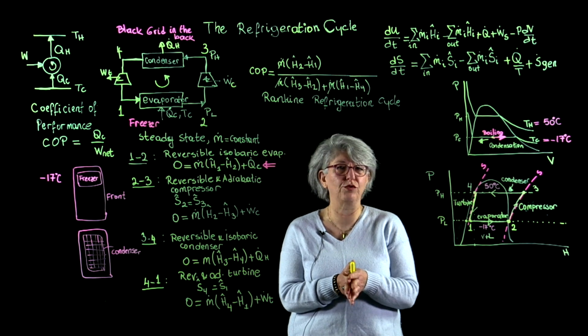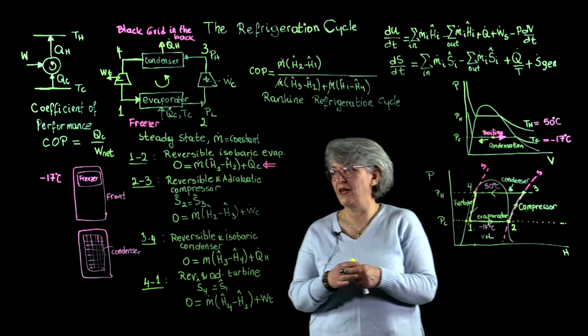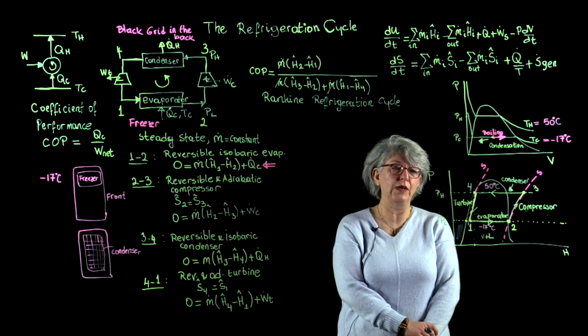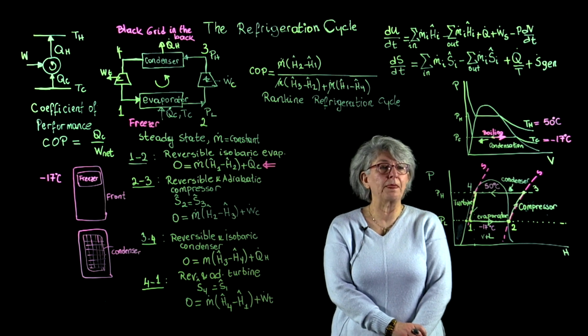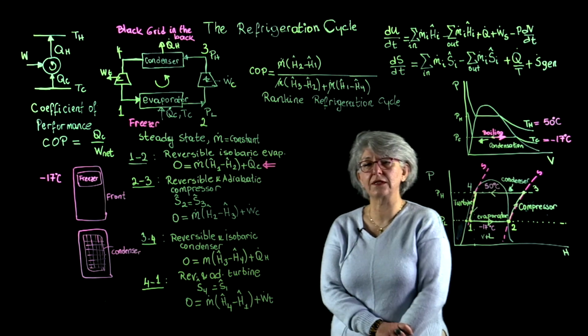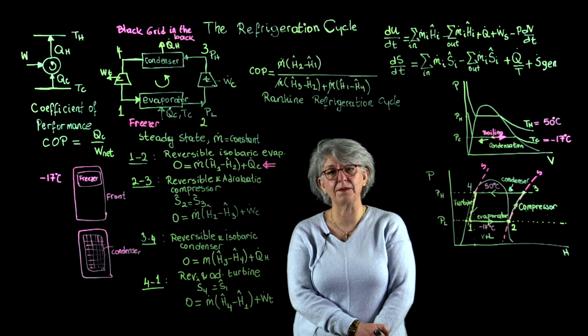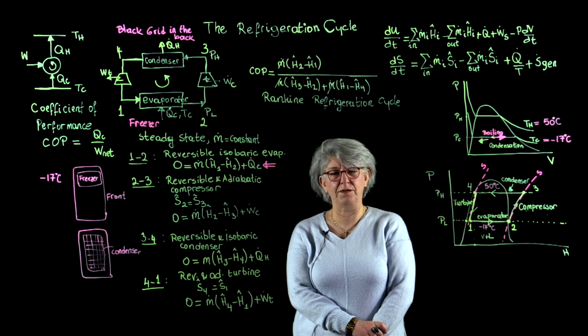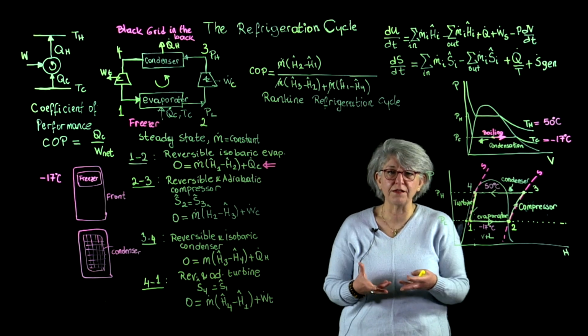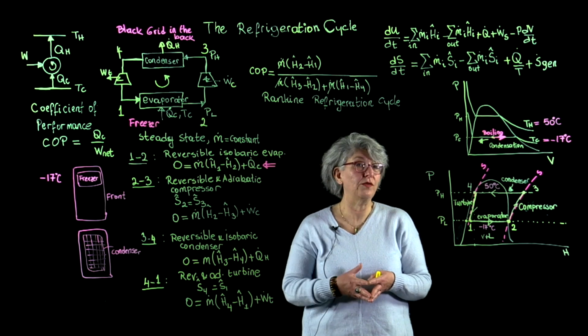This is very good in terms of our requirements. It's below minus 17. It's not too low than minus 17. And it also fulfills conditions of this high pressure behavior. But ammonia is a corrosive liquid, and the metallic components of the refrigerators couldn't withstand.